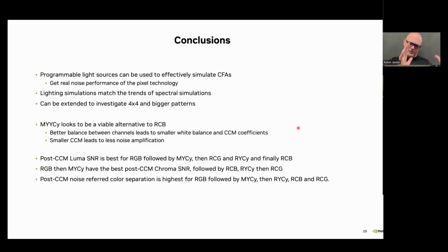It's a little bit less if you just look at brake lights and things like that. But capturing as big a dynamic range as you can helps you with flare around the sun. So if you have traffic lights behind the sun, it actually helps quite a bit to reduce the size of that flare. But at the same time, trying to get the low light response good enough that you can meet the requirements of something like FMVSS 127 is just super difficult.